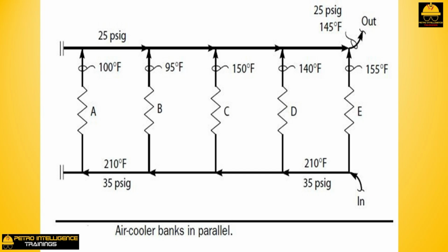3. Tube bundles nearest the inlet header tend to see perhaps 1% more flow than the tube bundles farthest from the inlet header. 4. Bundles seeing the lower flows have slightly lower outlet temperatures. 5. Lower temperature favors the sublimation of ammonium chloride vapor to a white salt-like solid. 6. This salt is very hygroscopic, meaning that it will absorb and condense water vapor from the flowing hydrocarbon vapor stream at unexpectedly high temperatures.